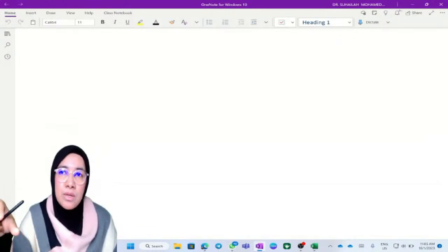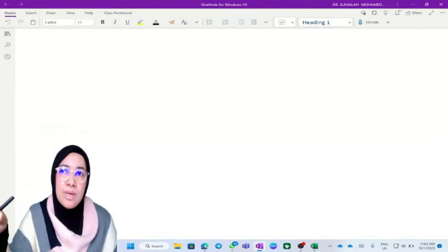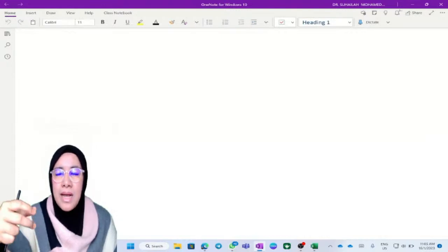So we do part A considering external loading only. So we have to include the joint moment, the applied moment subjected at the joint, for the first part. And when we do part number 2, we consider support settlement only. Then we add these two moments, and once we get the total member end moment considering both, we can continue to calculate the reaction, vertical reaction actually,